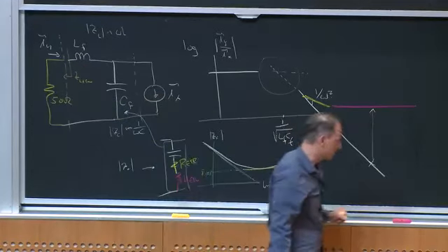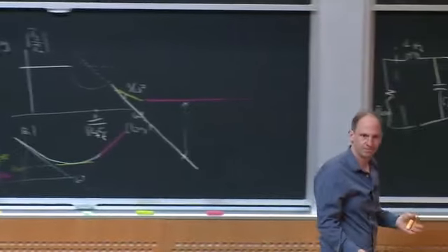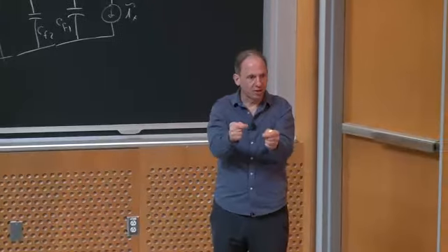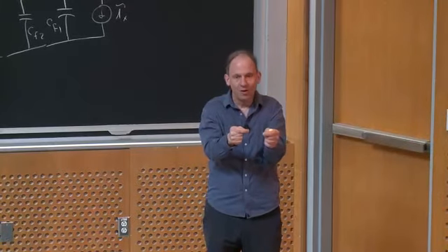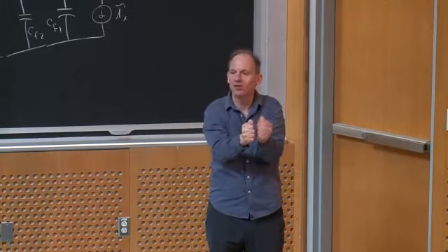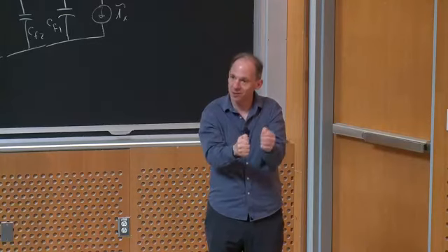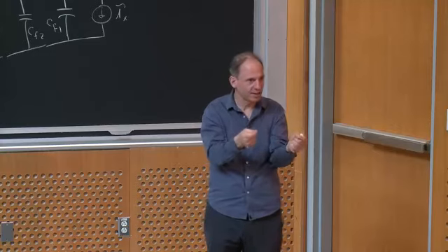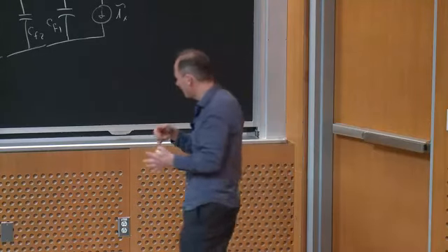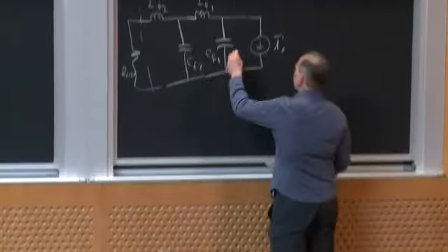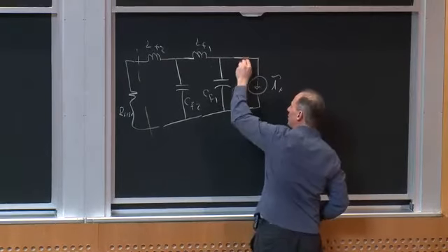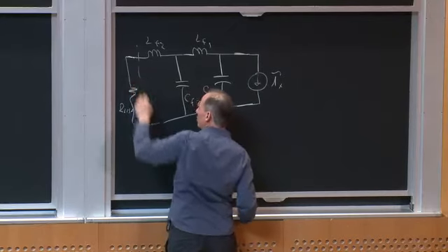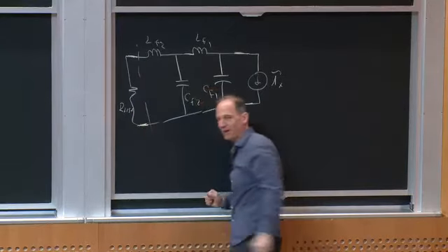But putting aside that parasitic, you also have layout parasitics, meaning if I do a crummy job and I don't stick the components into the board all the way, or I put two components next to each other, they can have capacitance between them, okay? So I can accidentally insert inductance, or I can accidentally insert capacitance. Imagine this is my power supply input leads, and over here is where it goes off to the power supply input, right?